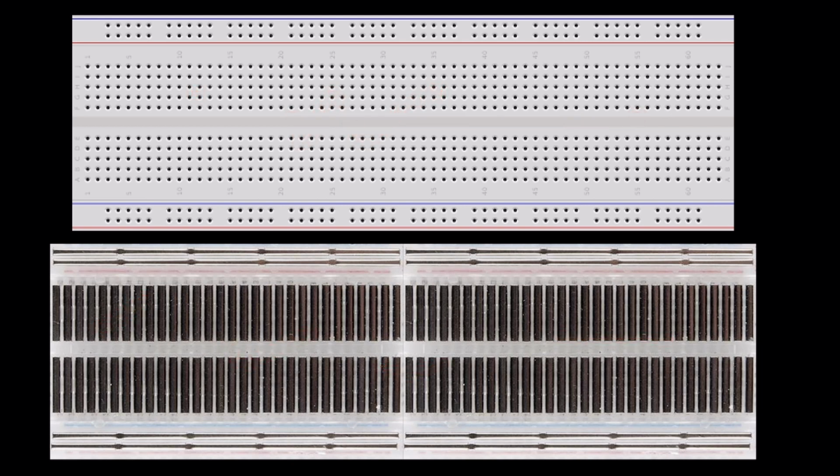That's why I told you that this line is power rail line 1, and this is power rail line 2. Here, I already told you, you can see there is some disconnection, right? That means this line and this line are not connected, so you need to use a wire to connect these 2 points. That means you will just do this short.